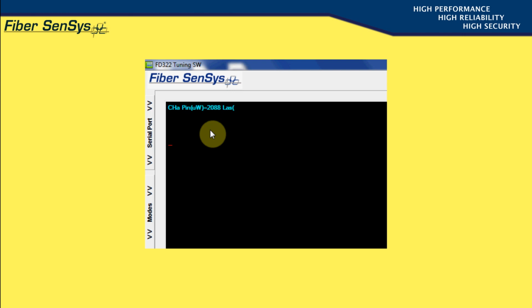As you can see, the status command gives you a lot of valuable information regarding the current health of your APU. You'll be using this command quite often during setup and maintenance of your sensors. The next terminal mode function we'll describe is the setup command, which provides access to a simple keyboard-driven APU parameter query and editing process. So let's type in setup to start our demonstration.